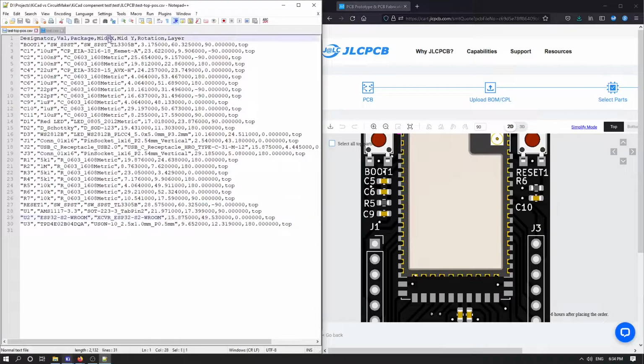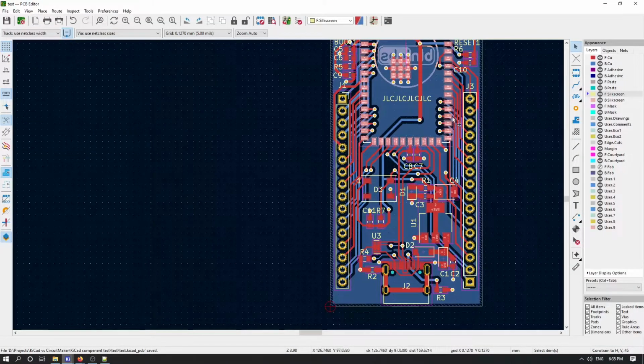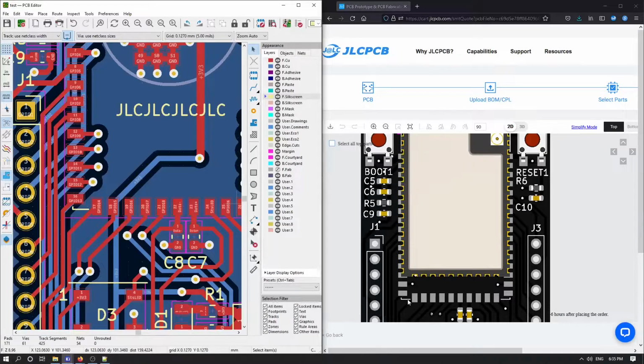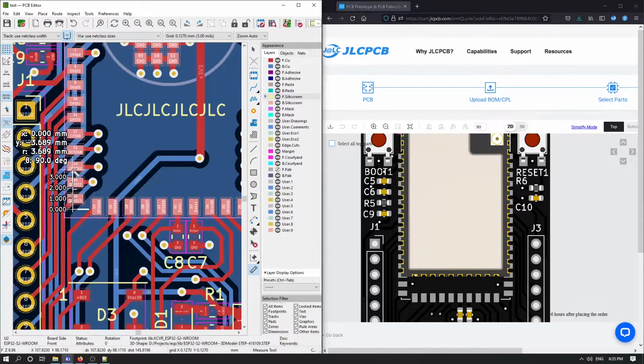these numbers here. So we should basically decrease our epsilon value. And by how much? Maybe we can determine that by going to actually our KiCad and maybe just taking a measurement from edge to, I think, the third one. But let's double check. So if we just take this line, 1, 2, this edge should be here. So if I just take now the measurement from this part to this part, we can see that this is something around 3.562 mils.